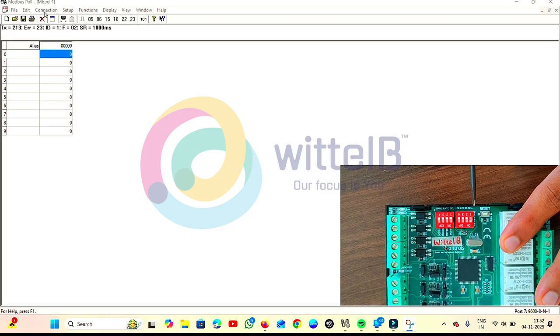Before changing the slave ID, this is the dip switch for the slave ID. In the dip switch they have marked 1, 2, 3, 4. That means the slave ID configuration is 1, 2, 4, 8. So if I need slave ID 3, then I need to hide the first and the second pin. That means 1 plus 2 will be slave ID 3. Then I need the baud rate as 19200. The first pin marked on the board is 19200, so I will hide this pin. Now I need to press the reset, so the board will take the new configuration.